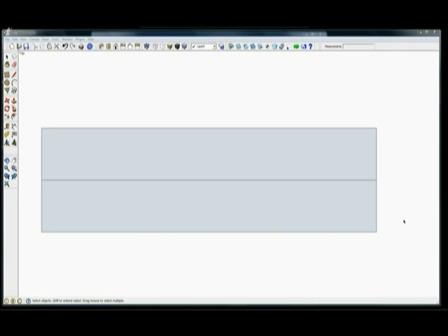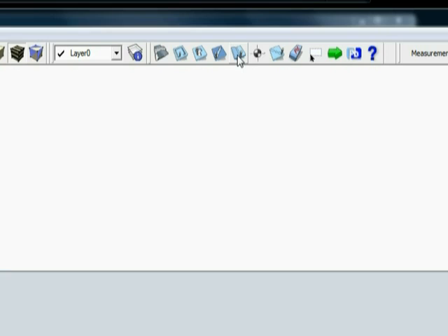You're going to like this next tool that we have in the PhlatScript toolbox here. We're going to talk now about the fold tool. Let's say you have a piece of foam. If you've ever tried to bend an extruded polystyrene sheet like Depron or fan fold foam, or one of those rigid foam sheets, you know that to bend that foam maybe back on itself for a KF step, or to bend it 90 degrees for maybe a three-dimensional shape box style fuselage, well, you know that you have